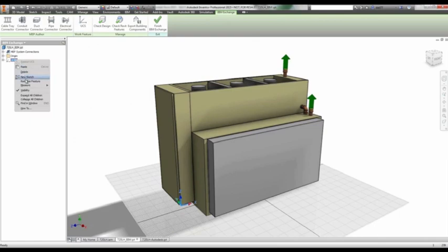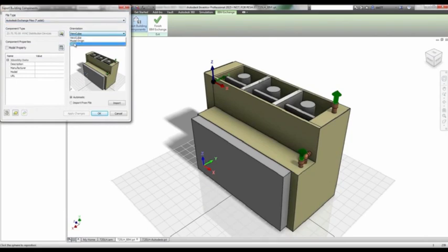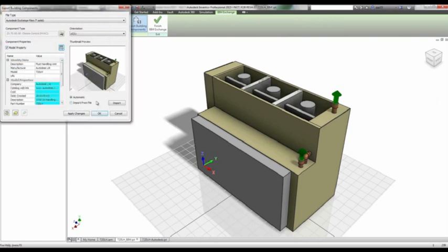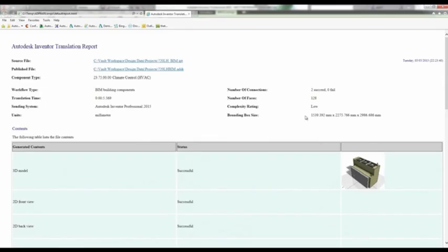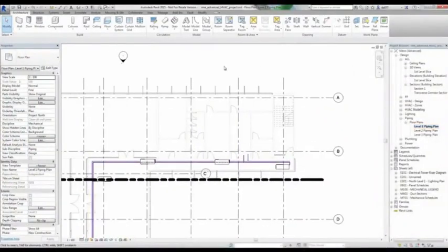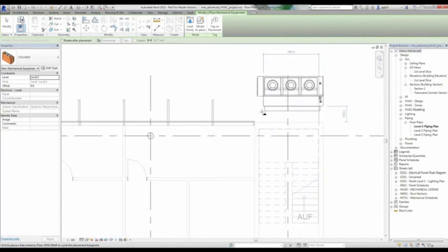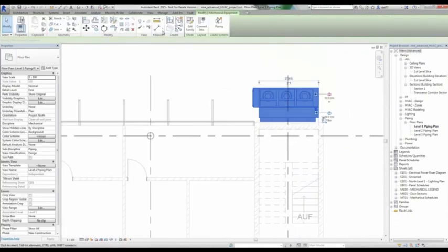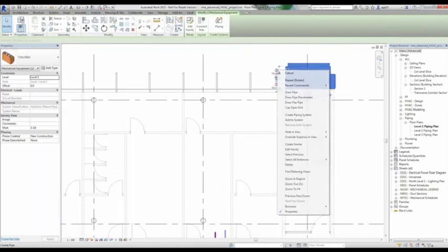The important bit though is the outside, in so much as the dimensions are still physically correct and such like, and I've still got the connection points as you can see me adding here. So from an extremities point of view, the model is still the same. I'm now placing my orientations and configuring the model to be consumed inside of Revit. I'm now doing my classification, then adding metadata into the file so that maybe my company information about where this needs to be mounted and such like, so that all of that information is embedded in the actual file. And once that's done, I can export that out as a Revit file in this case.